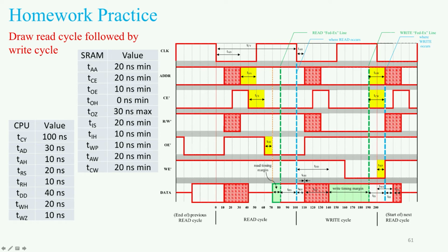this time frame. To figure that out, we first have to understand when the SRAM flips off, and that's determined by output enable. Again, output enable in this case transitions because the clock falls. Falling of the clock, 10 nanoseconds later, because of glue logic, you've got output enable flipping high.